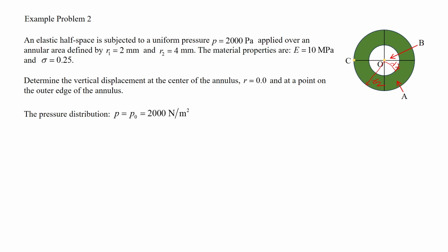So, how do I solve it? We have to consider as if the load is being applied through the shaded area only. So, we will use the principle of superposition. We will consider V at z equal to 0 because of the area through which the load is applied, that is A, which is compressive, minus V at z equal to 0 for area B, let us say it is tensile, something like that.